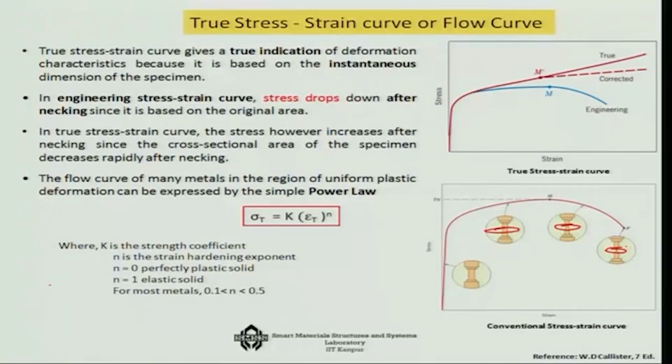So, the area is changing, and if you consider that actual area, you will see that the stress strain curve is not drooping, but it is actually increasing, and it is increasing because even if the force is increasing, the area is decreasing at a very rapid rate. So, that is why the true stress is increasing at a very rapid rate.